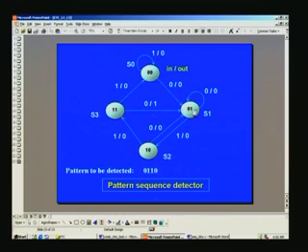And looking at the state here, we are in S3. So, if input is 1, it should take you to S0 state, and otherwise it should take you to S1. So, just remember S0 and S1 for input equal to 1 and 0.